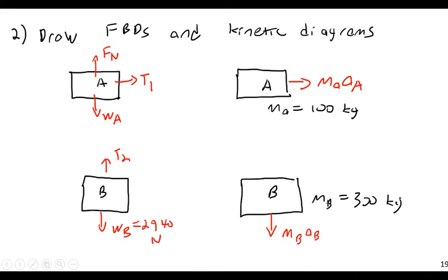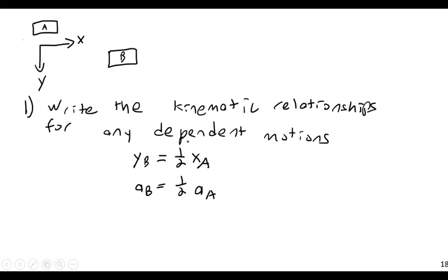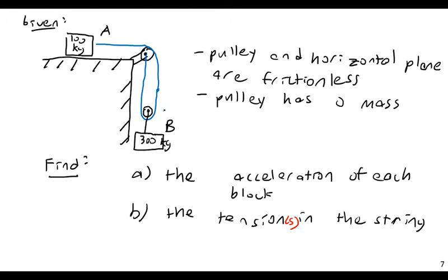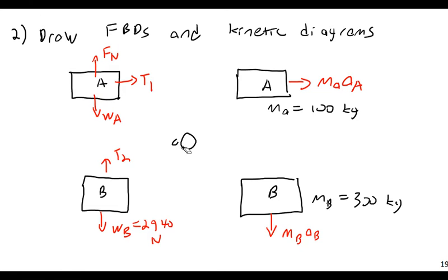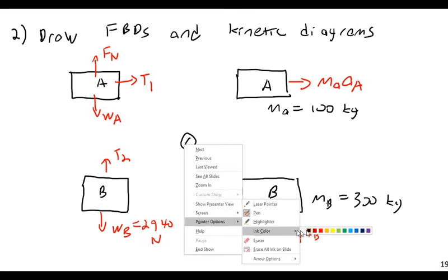And then I might have one other thing that I'm not going to bother finding an inertial diagram for, because it doesn't have a mass. We actually indicated that it doesn't have a mass. But point C here would be the pulley itself. So let me label this point here as C and make clear I'm talking about B here for the block. For pulley C, if I look at the forces on this, things are a little more complicated.